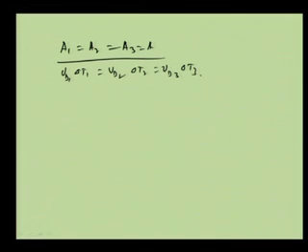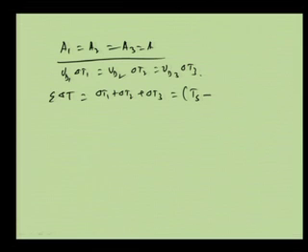From there we can write that summation of delta T, delta T1 plus delta T2 plus delta T3, is equal to Ts, the external steam saturation temperature, minus Tw3, minus the summation of all the boiling point elevations. This can be proved if we put in the values. And the summation of boiling point elevations we have already seen.